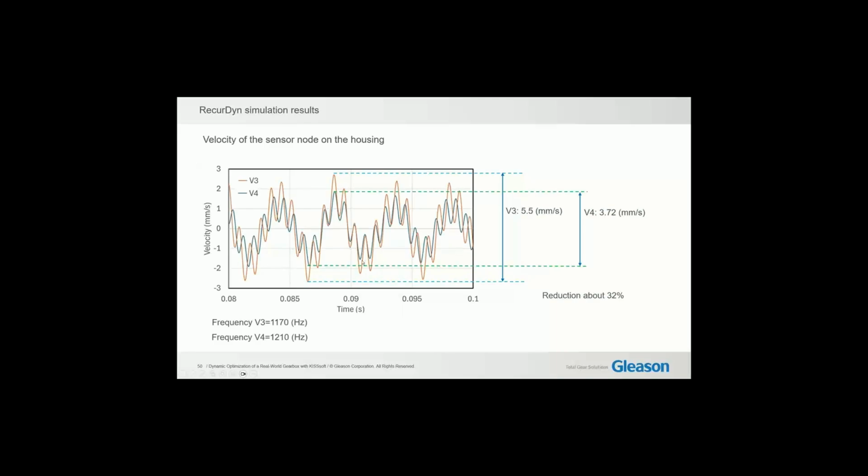Another important fact which can be seen from this figure is the frequency. If we consider, for example, a point where the peak values are over each other, and then we count the number of oscillations and divide over the time, we can simply calculate the frequencies. And here we realize that the results catch exactly the frequencies reported in the experiment. So based on this simple result, we can identify the amplitudes as well as the frequencies.